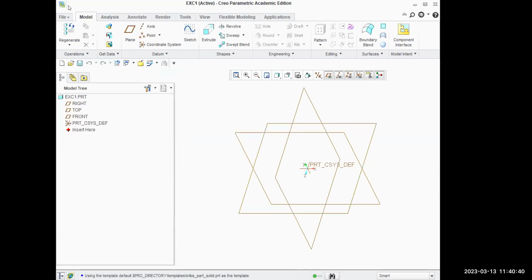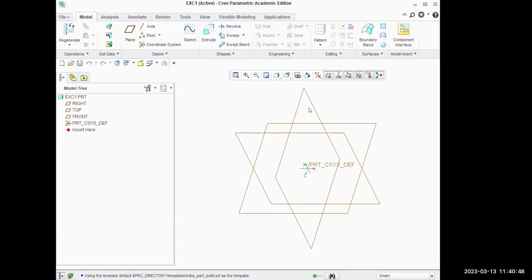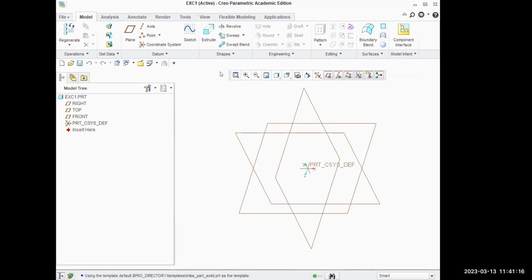Okay. So this is the part model. Part modeling. Several tabs will be there, and we'll try to explore them. Here, one shortcut you can note in order to pan the screen: press and hold shift and the middle button of the mouse, then move your mouse. To get it back into the visible screen, you just need to click on the Refit option.